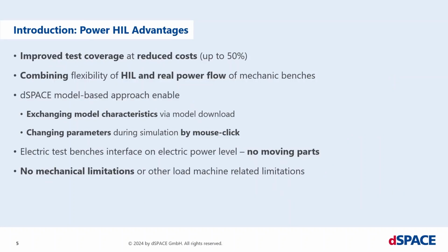So we have an improved test coverage compared to signal hardware in the loop, because now we can test on full power level, and we have reduced cost compared to our mechatronic test bench, and especially compared to our real prototype that we had to set up if we do not have power hardware in the loop. We combine the flexibility of hardware in the loop testing at full power.